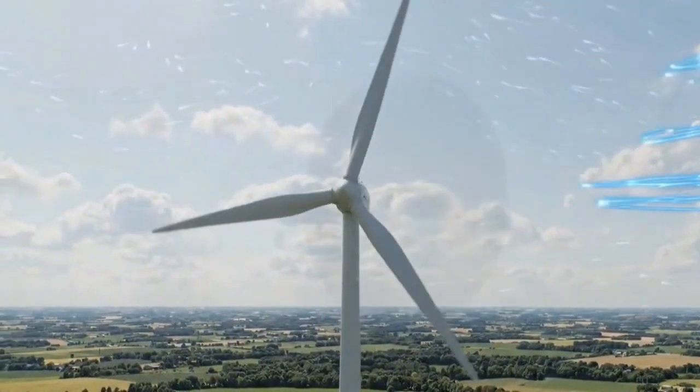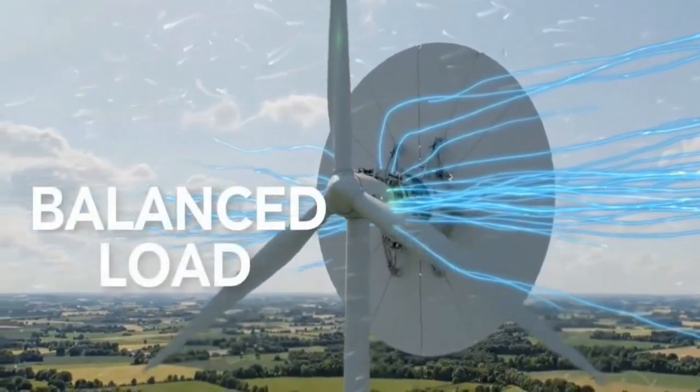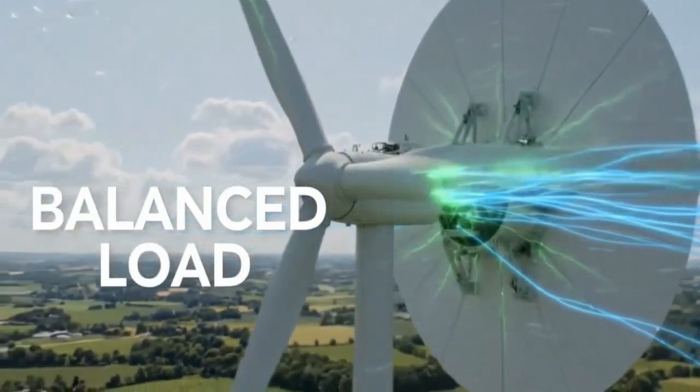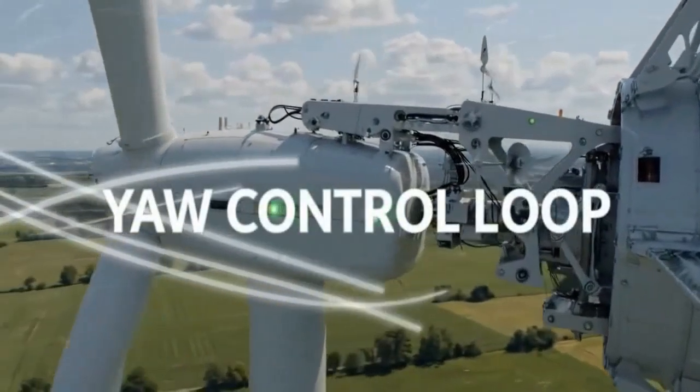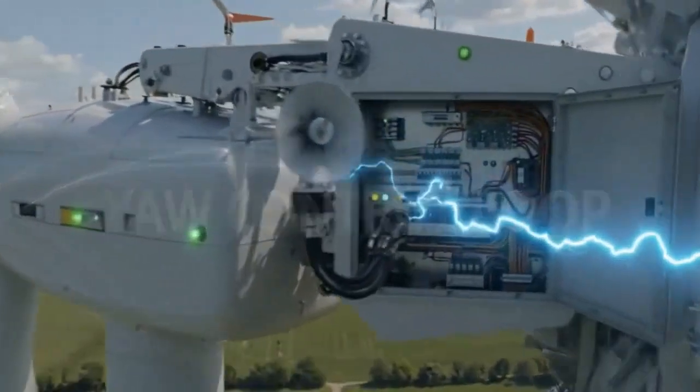At the same time, the blades move into a feathered position so wind passes with less turning force. As the rotor nearly stops, the turbine enters a safe state, reducing load on the gearbox, shafts, and generator.